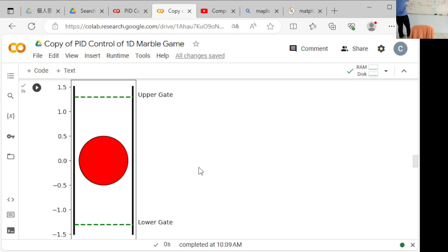You have to realize that you're dealing with motion under constant acceleration, and the way to be able to do that is, what's the crucial piece of information you actually need here in order to come up with a reasonable control, in order to avoid unbounded oscillation, in order to avoid increasing the velocity of the ball as it's shooting through the tube?